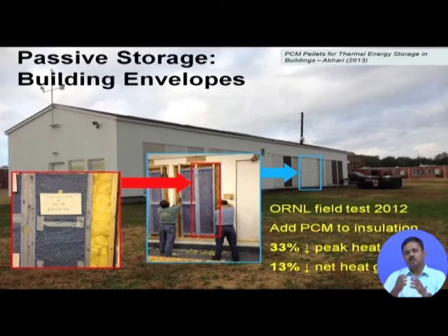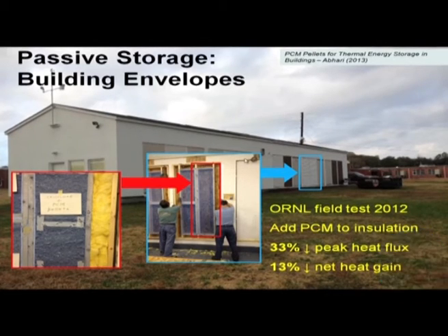So, during night the PCM solidifies, and as it solidifies it gives up heat maybe to the outside and the inside of the room, and that keeps you warm, which is not bad. And during the daytime when the temperature goes up, it absorbs the heat and prevents it from going inside. It absorbs the heat at the wall itself and melts, and therefore it does not go through the wall into the inside of the building. So, the air conditioning load goes down because the temperature inside the room is already reduced to a certain extent. The heat load that needs to be removed is less.